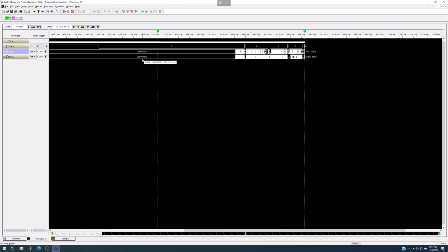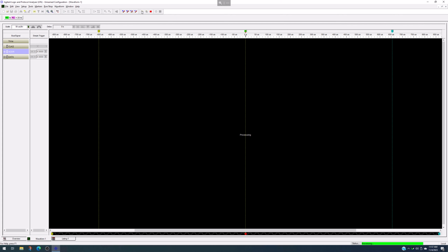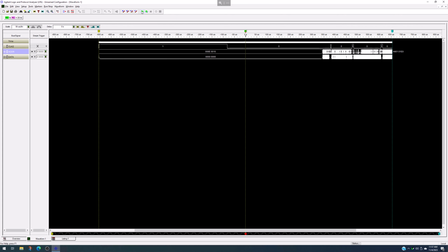Okay, that seems okay. So then I can go ahead and maybe run this again and see what we capture. And there's an E10. There's 5AC. Now 5AC is a memory location low in RAM, and this read a 1C05. And so that's a spot where I'm trying to write back a value after I've incremented it. I'll then read it, increment it, write it. So we'll see this spot maybe show up a bunch, 5AC.